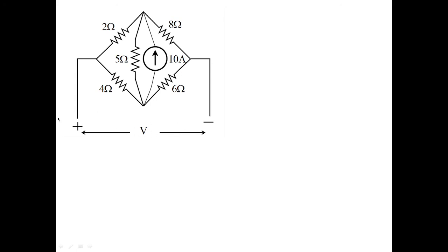Since it's a current source, that's why we have open circuited. If at all it would have been a voltage source, then we would have short circuited this particular point. Since it was a current source, we have open circuited it. Now we can estimate the value of voltage over here. Now this voltage should be equivalent to 5.42. So how are we going to solve this?